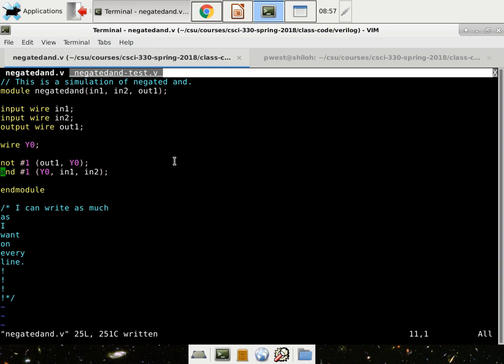Is anyone confused by that? If you put a 2 for the NOT part, would it take one tick longer, or would the AND then take longer? No, because in this case, the NOT is coming after the AND. You can see by the fact that the output of AND is an input up here. If these were not connected and they were completely separate, then it would only take 2 ticks in total. Good question. So basically, since the NOT relies on the AND, you just add the number of ticks from the AND to the NOT. Correct. But if we had a very complex circuit where we had different things going in parallel, you have to go and evaluate the longest path, which we'll get to later on.